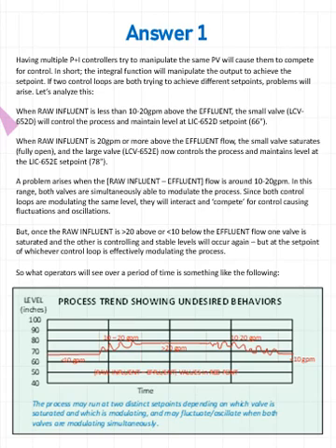So what's going to happen is it's actually going to wait. It's not going to do anything until level rises up to 78 inches or close to it. And then it's going to start to control to keep level at 78 inches, because that's what a PI control loop does. It tries to maintain the set point you tell it. So we have a problem that arises.